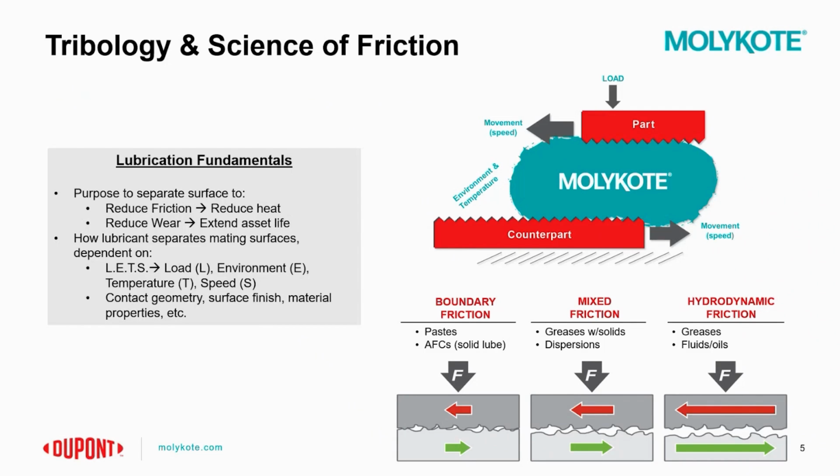The load being applied to two moving surfaces, as well as the speed at which the two interfaces are moving, if at all moving, is important to consider. A high load at a slow speed may warrant the use of a paste, whereas a low load at a high speed may warrant the use of a grease in contrast. Additionally, some applications at more extreme conditions would also require additional, more specialized additives.